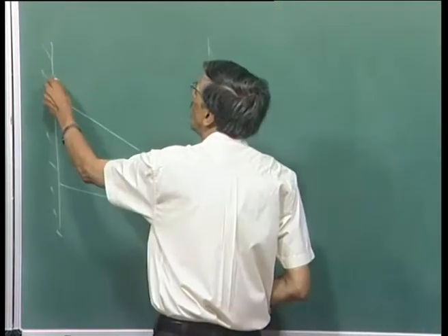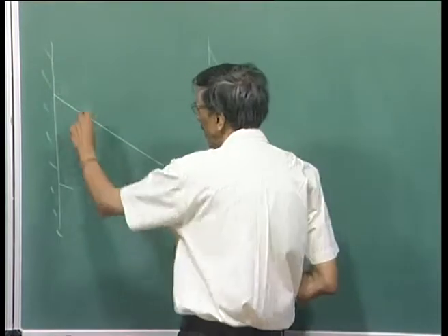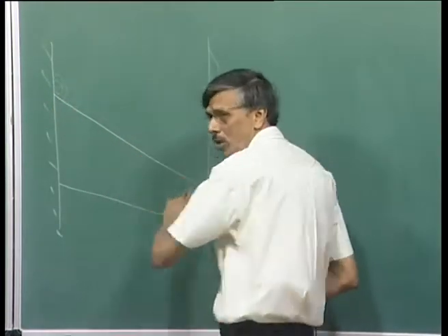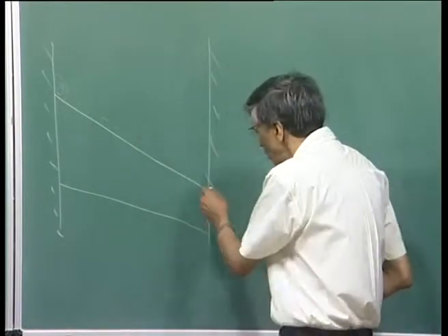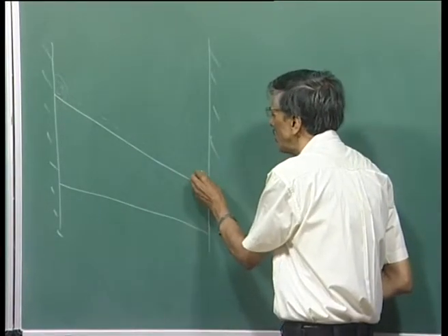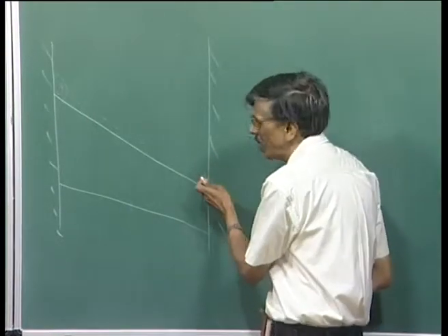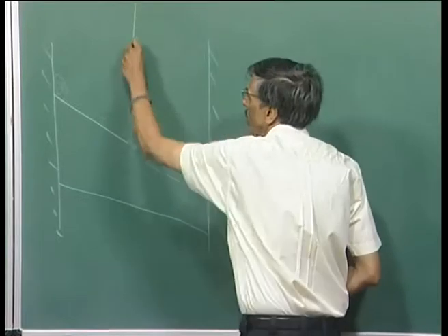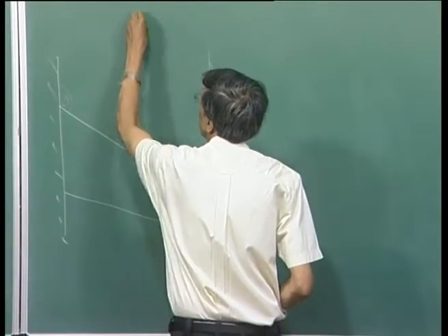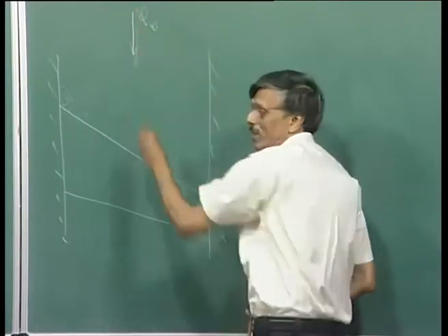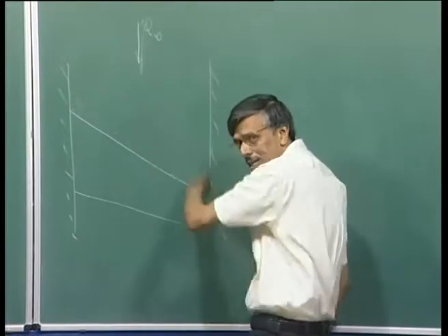And then of course, you will have vortical structures forming there that migrate along the spanwise direction. You would also have similar vortical structures created here, corner vortices, but the oncoming flow is what we are drawing there as q infinity, right, and that we split into u infinity and w infinity, right.